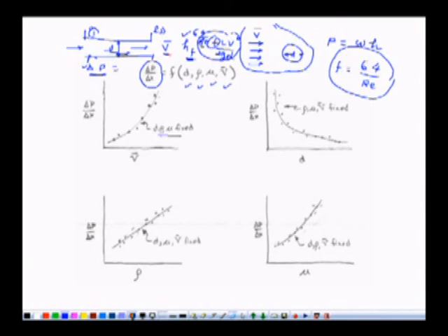So, you can conduct this experiment, allow the water to flow through this pipe at different velocities, find out del P over del X, which can be measured, and measure the velocity also. This can be measured with the help of a simple relationship: if flow rate is measured with the help of some suitable device or by collecting water in a tank for a given time, you can find out Q. So, Q is equal to area into average velocity.